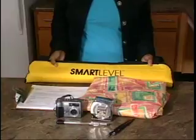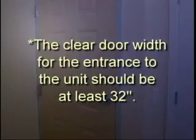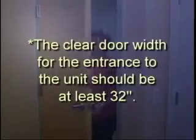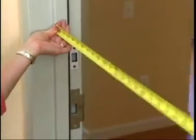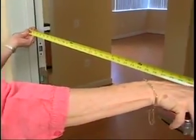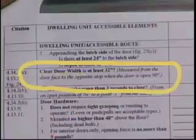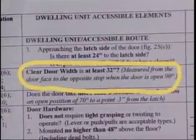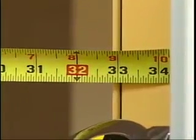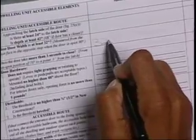We will start with the entrance to the unit by measuring the clear opening of the door. The clear door width for the entrance to the unit should be at least 32 inches. Keep in mind that we need to keep the measuring tape horizontal and measure between the face of the door to the opposite stop with the door open 90 degrees. As noted on the checklist, the clear door width should be at least 32 inches. And as you can see here, the door width to this unit measures 32 7/8 inches. And that's what's entered on the checklist.